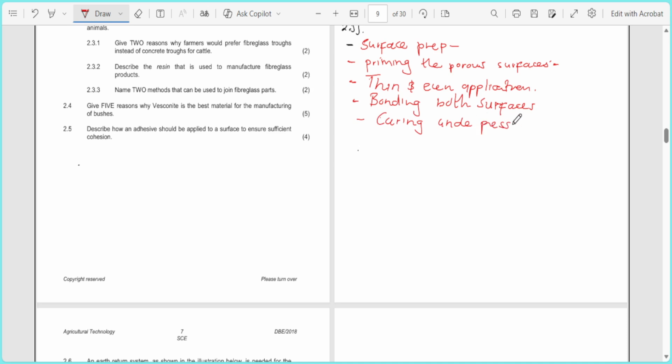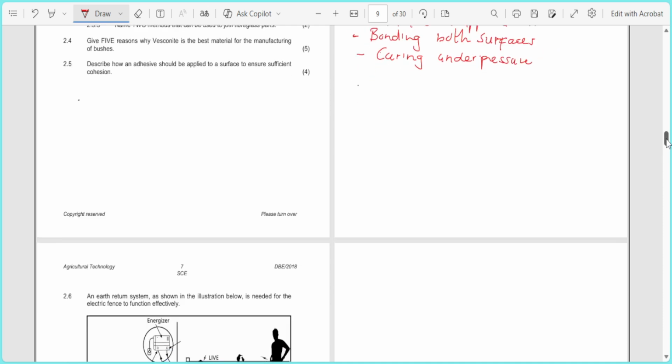Now that the two surfaces have been bonded together, it's time to allow the adhesive to start curing and securing the two materials once bonded. This will maintain the intimate contact during the curing process. This will eventually prevent air pockets and ensure a continuous bond. So after bonding the two surfaces, they should be maintained in that position so that no air seeps in and compromises the bond between the two bonded surfaces.